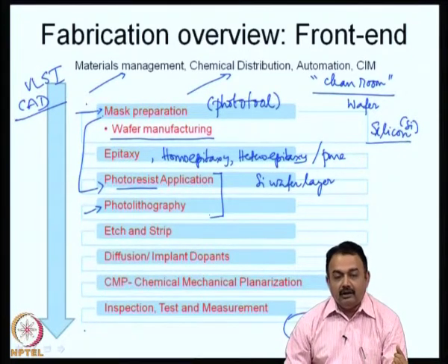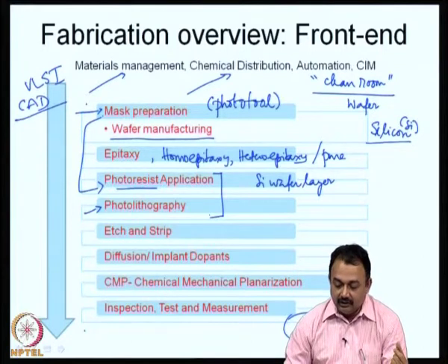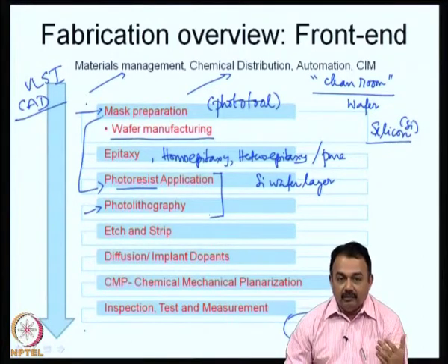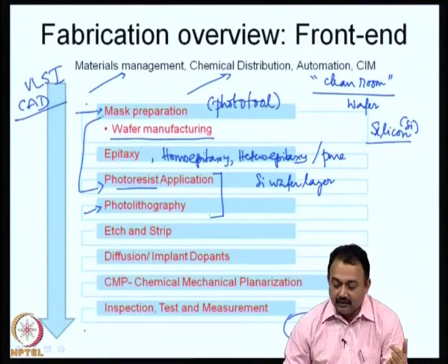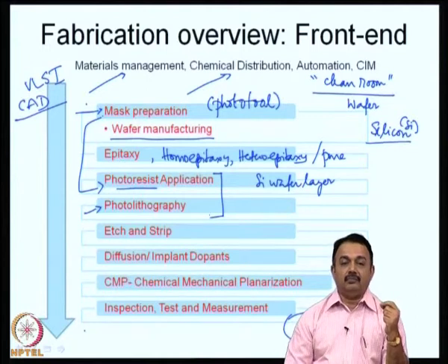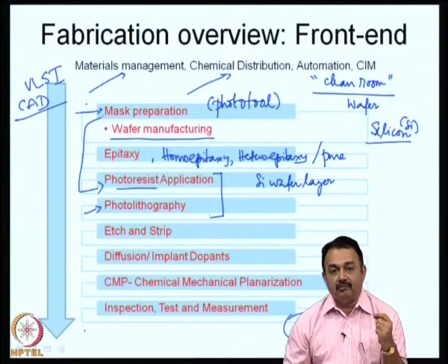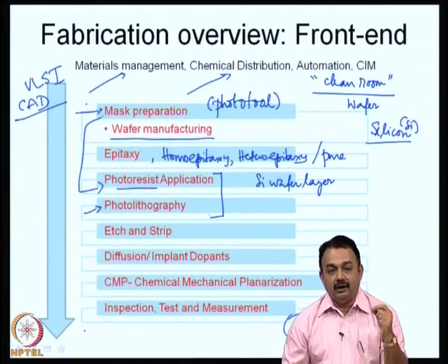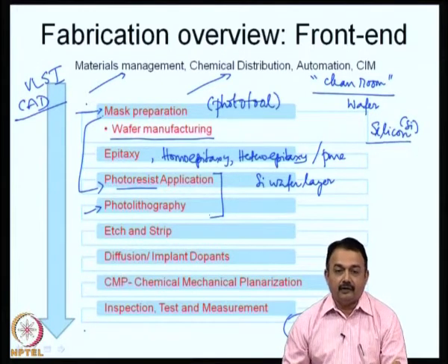So, typically currently the industry uses a wet process for photoresist application, and there will be a dry imaging process that follows the wet process of application of a photoresist, and therefore, the resolution that is got from the photoresist is very important in defining the yield rate from every wafer.